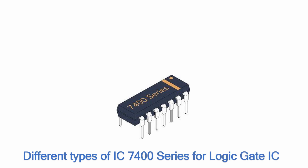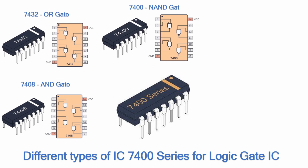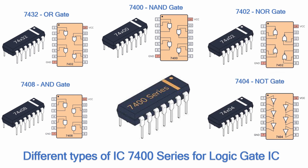This particular IC, known as the 74 series IC, is designed for logic gates and has 14 pins, 16 pins, or 24 pins. The different numbers are for different sets of gates, such as 7408 for an AND gate, 7432 for an OR gate, 7400 for a NAND gate, 7402 for a NOR gate, 7404 for a NOT gate. For now, we choose a 14 pin IC to start learning today.